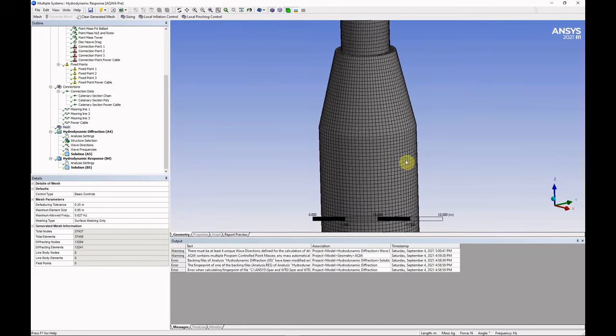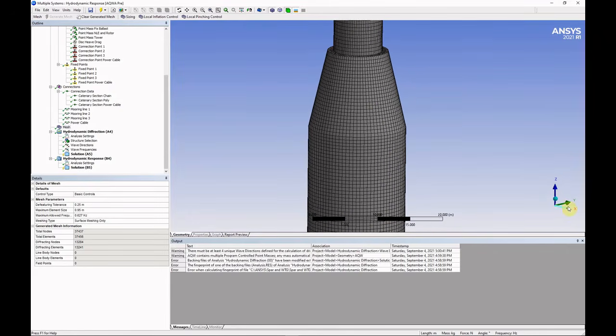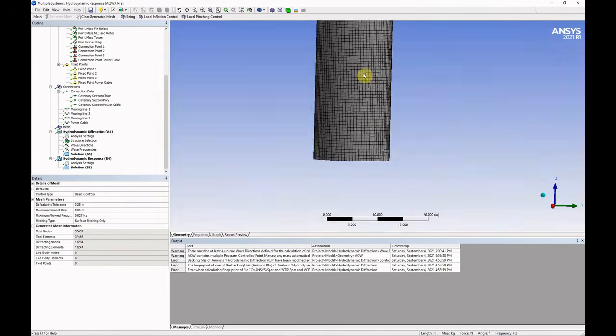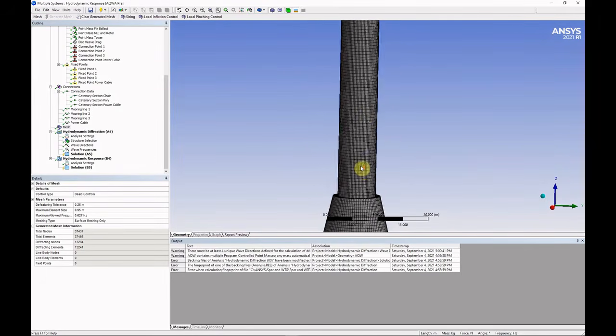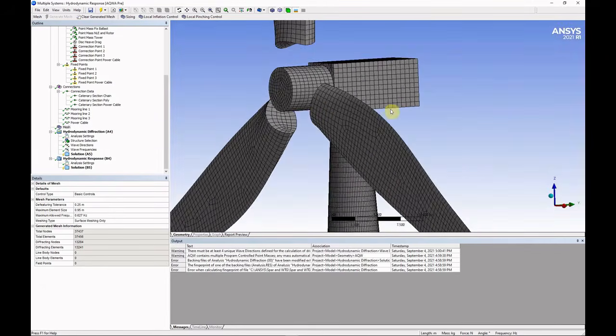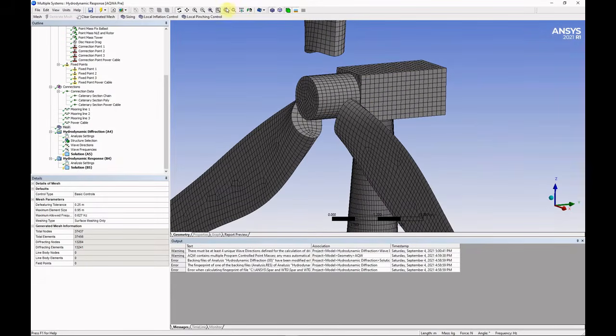Check that the mesh in the submerged hull is correct everywhere to provide a closed volume which will be used to calculate the hydrostatic displacement. The elements above water are not important. We added top structure only for visualization, not for actual calculation.